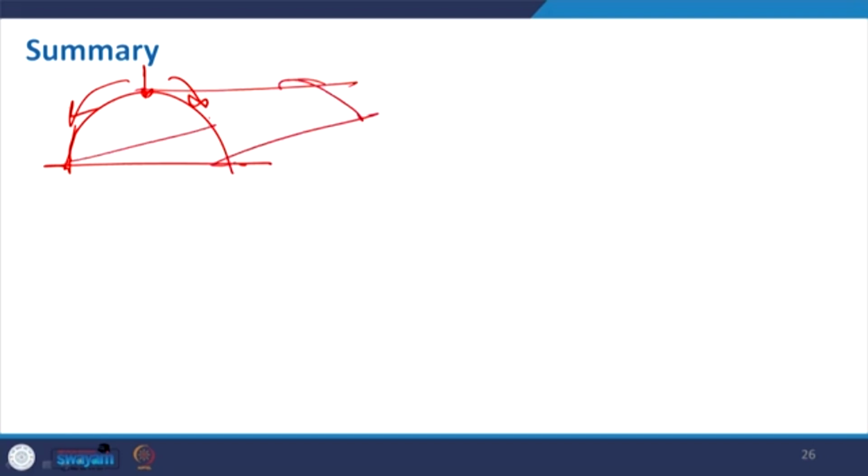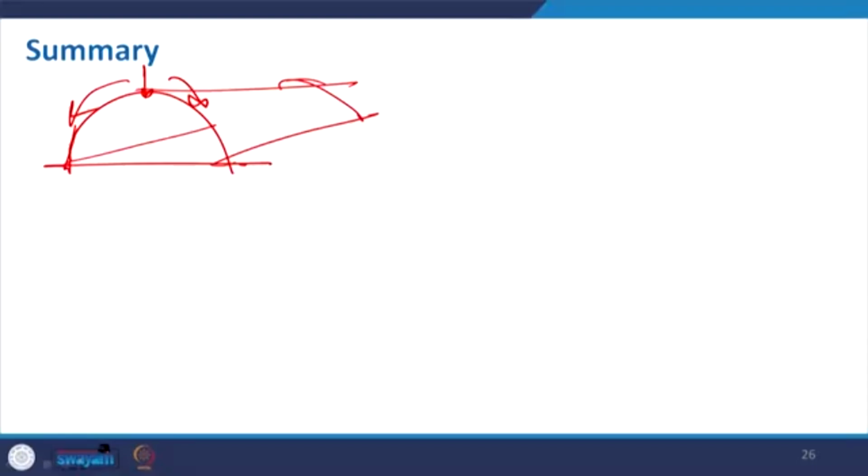So, now we are coming to the end of this lecture. What exactly do we summarize, if we want to summarize here? We started with the vault. This vault is basically evolved from arches. We know the property of the arch, and in this arch, from the keystone, the load is being distributed, and then we extend it. That will become the vault, and vaults are also capable enough to take care of a long span without much vertical support, so that we can create an obstruction-free space.